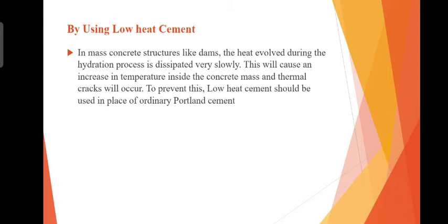To prevent this, we use low heat cement for dams in place of ordinary Portland cement. In OPC, tricalcium silicate and tricalcium aluminate are mainly the reason cracks occur.